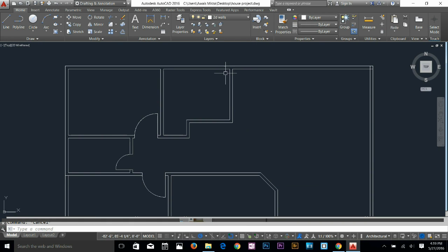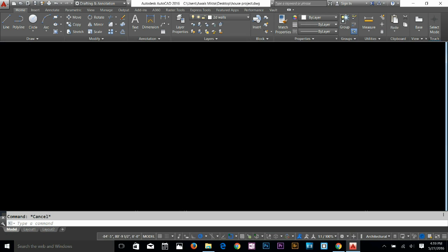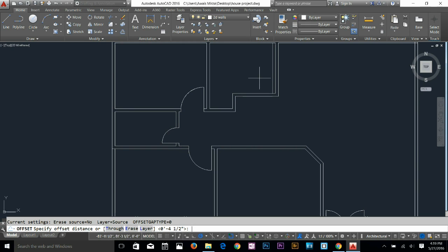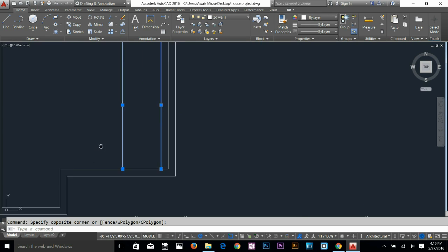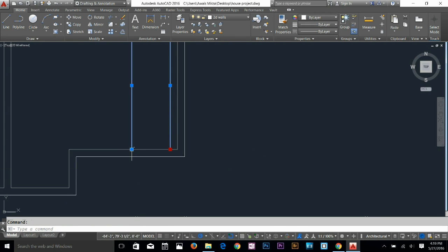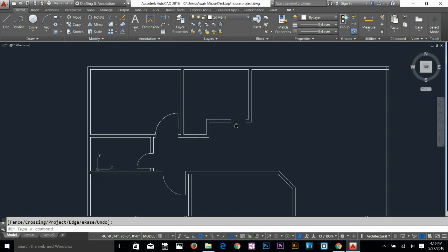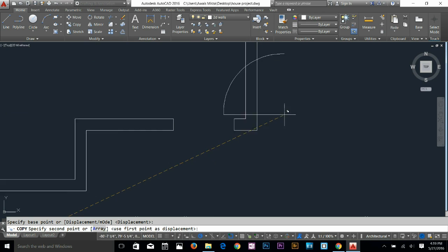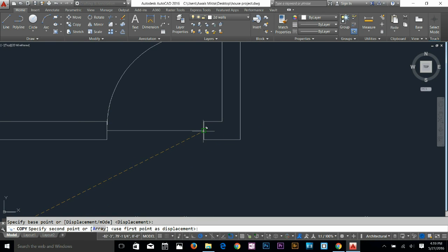Okay, so we can make a door here now. I want to take the same door there, so I have to make a cutting edge, so 4.5 inch, offset about 2 feet is fine, and then select both lines, hold down your shift key, select this vertex first, and then leave your shift key, select that vertex and just drop it down. Trim these lines, and then you can just copy this door from here and maybe just drop it there, and then